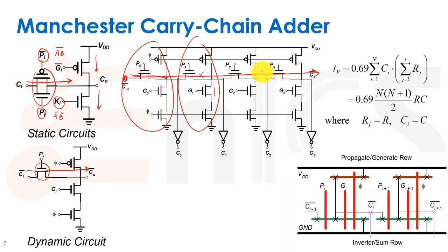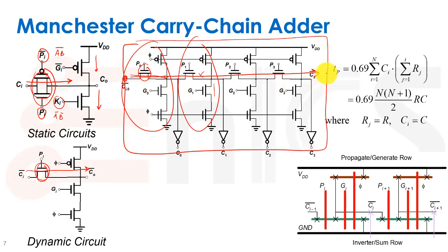Okay, so this is going to be our Manchester carry chain, and it's really, really fast. Can we put 32 of these in series? And the answer is probably not, because remember that each of these pass gates, if it's one like this or one like this, adds serial resistance, and we get a large increase in propagation delay due to the serial resistance. So every once in a while, we're going to take finite sizes of this, such as 4 of these together, and buffer the carry after that. But that's a really cool way of doing this, a Manchester carry chain, and you can make a very fast type of adder in that way.